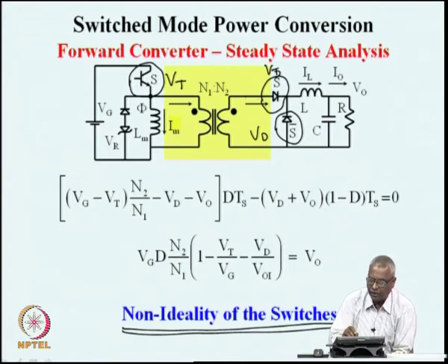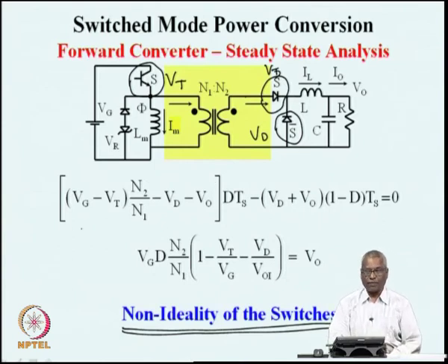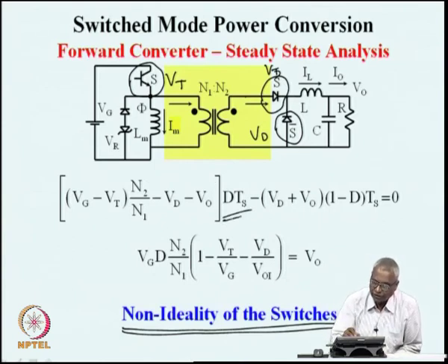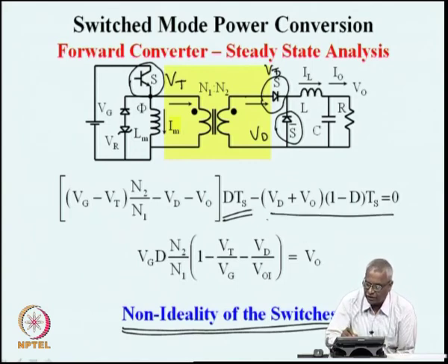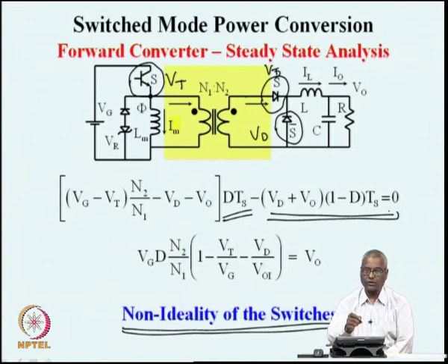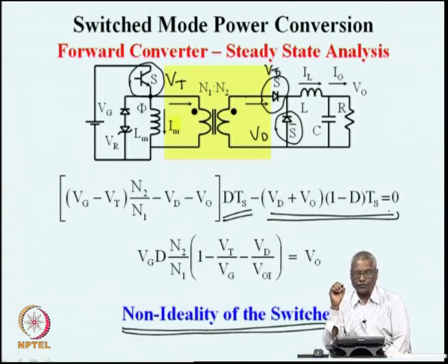From that you subtract one diode drop Vd, and then on the other side is voltage V0, so you subtract another V0. This is the voltage applied across the inductor for the on duration, and similarly the voltage applied across the inductor during the off duration.